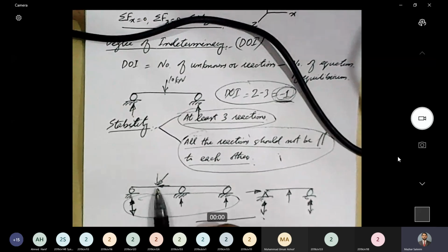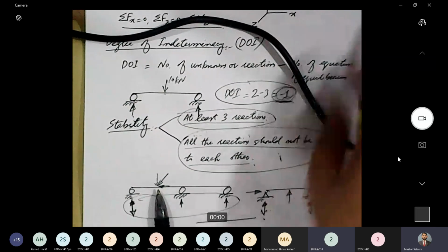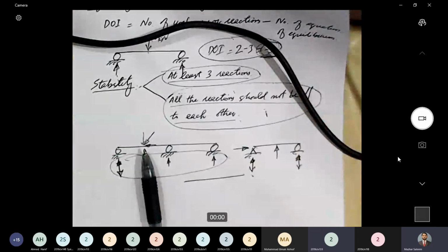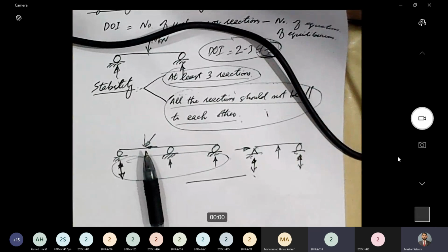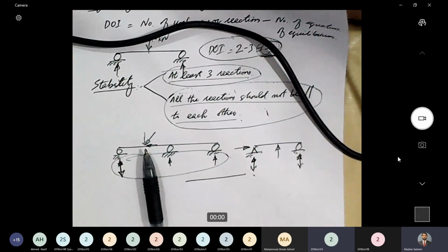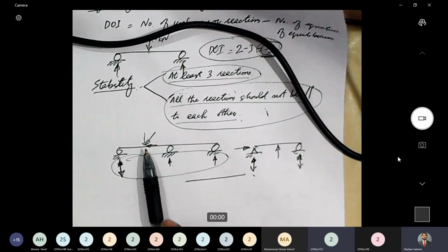Okay. But sir, in such a case, wouldn't that beam be acting against the reactions of gravity, and wouldn't that make it a bit more susceptible to instability? No, as long as the supports do not fail, because there is another parameter, which is the strength of the support.